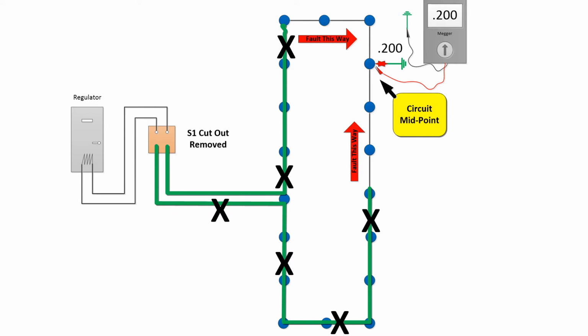And we break the circuit again, and at this point, 85% of the circuit has been tested by only doing 3 tests. We might have to keep zeroing in on it. It may take several more tests depending on how many lights are in that portion. But you can zero in on it very quickly if you very carefully split the circuit in half each time.